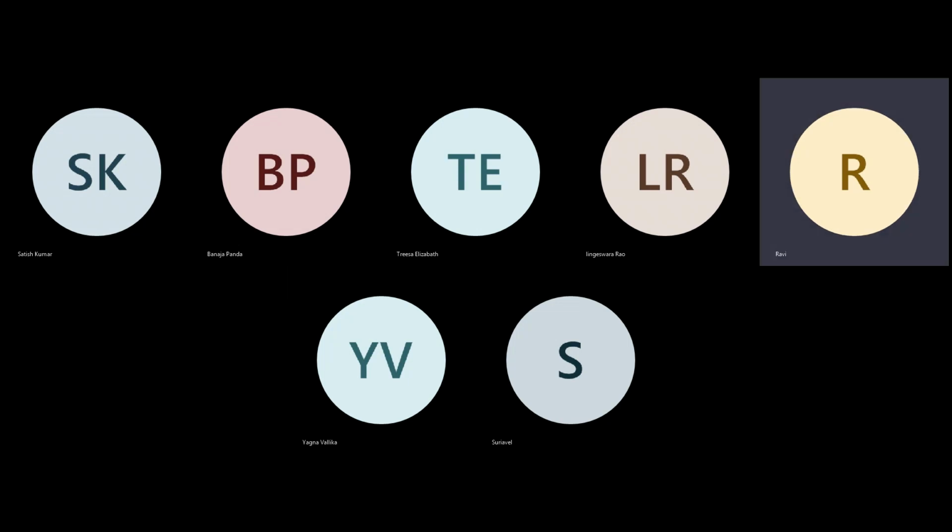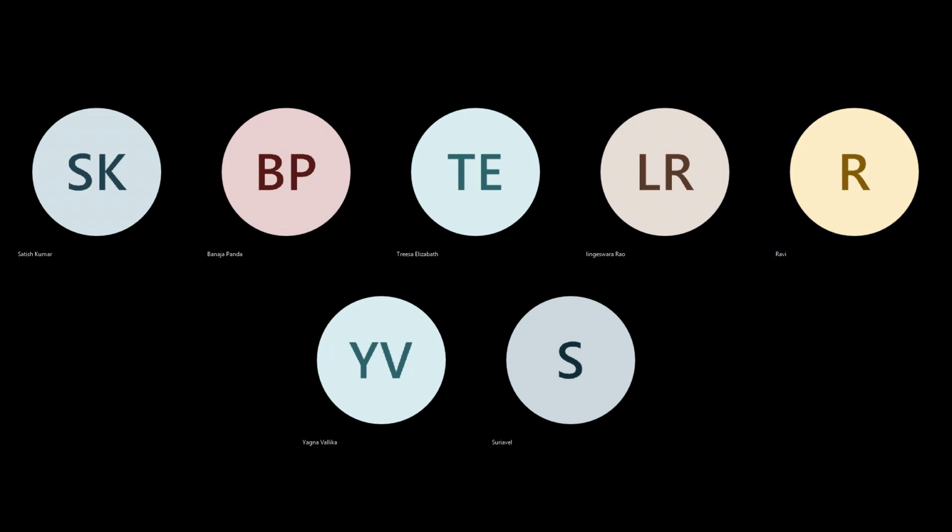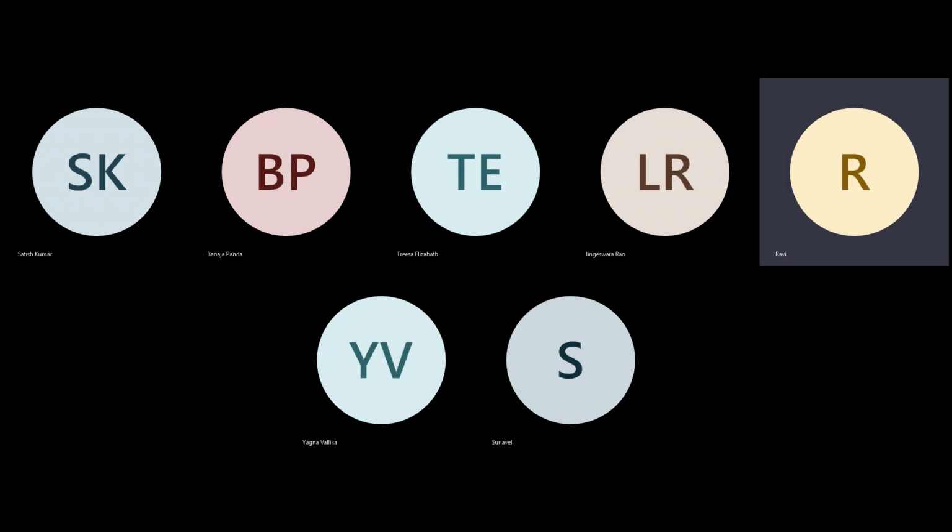You cannot use thin and narrow memory like this. What will happen is one cell will sit there, one cell will sit there, and eventually the timing will have a problem. The module will get split, it will be very difficult. You will see access time is less, but eventually for your timing closure and congestion for your floor planning, I've seen somebody adding memories, and that memory is going outside the plan. Then you have to re-change.